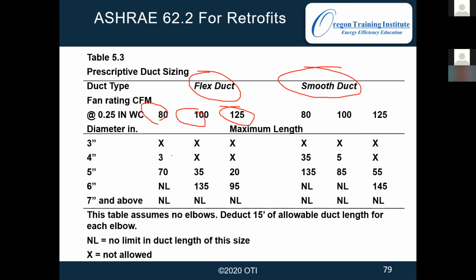If we vented it with a 14-inch duct, the fan's probably not going to be strong enough to push it all the way out, but there wouldn't be any restriction from the ductwork itself. But I would recommend going 5-6 inch as a default, and that's going to keep you in the clear most of the time. We're not going to have flow restrictions.